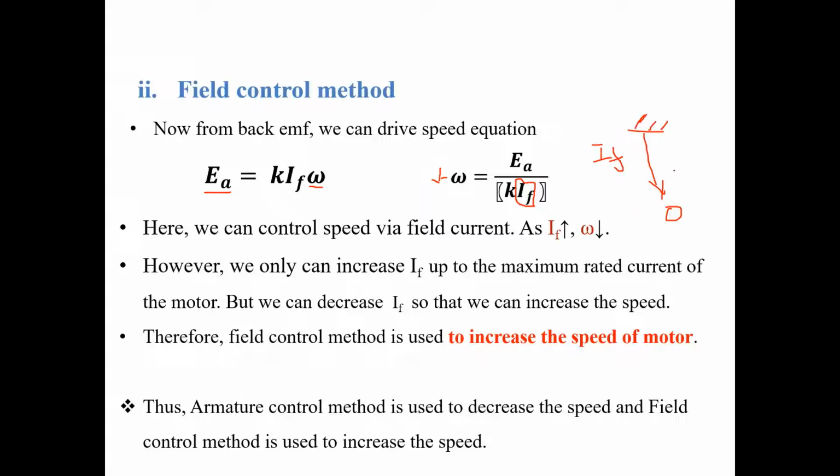So if we keep decreasing the field current to 0, the speed keeps increasing, because as I_F approaches 0, the speed approaches infinity.